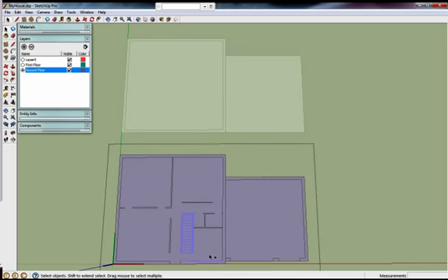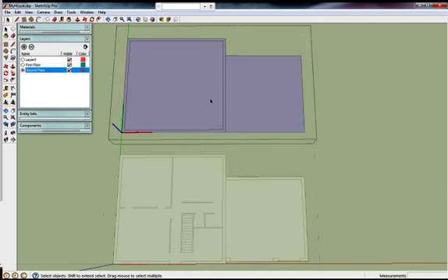If you hadn't noticed, I deleted the stairs on the second floor when I should have left them in place. To fix this, go into the first floor component, copy the stairs and a line from the outside wall to assist us in placing the stairs on the second floor. Then enter the second floor component, paste the stairs inside the floor, and using the reference line we copied, move the stairs into position.